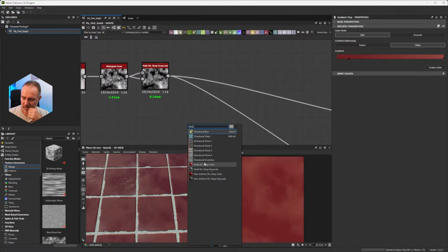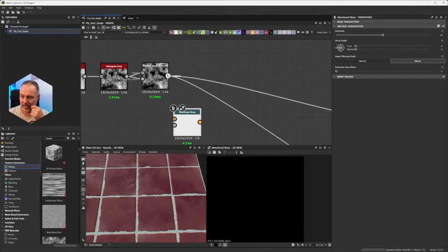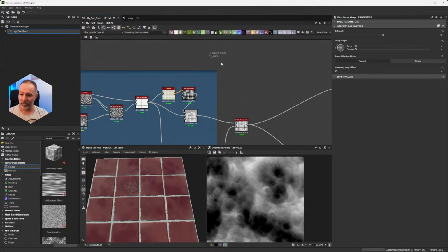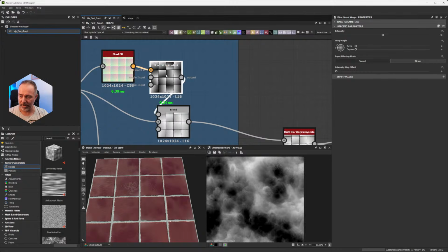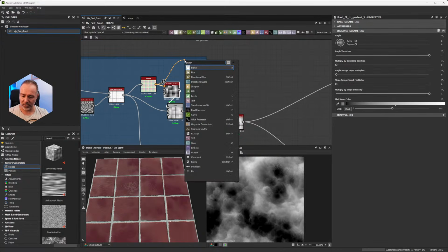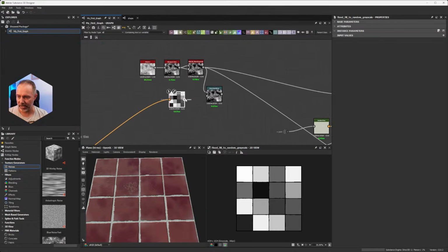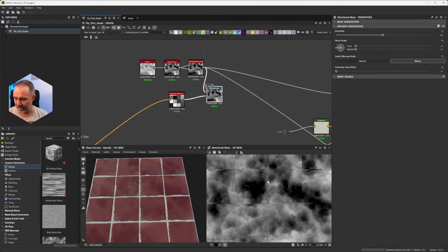What it does, it will push in a single direction, but with different intensities. So, directional warp here. I'm going to take this, and what I want is to define a different intensity for each tile. To do this, it means a different grayscale value for each tile. So if I'm going back here with the float fill that we made, there is another utility, make float fill to random color grayscale. And you see, I have different values, different colors, meaning different values for each tile.